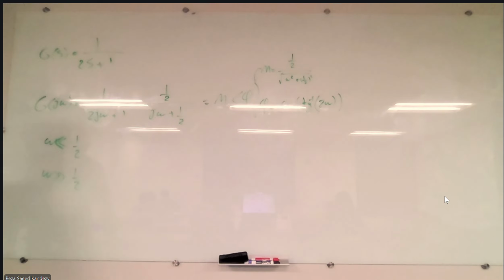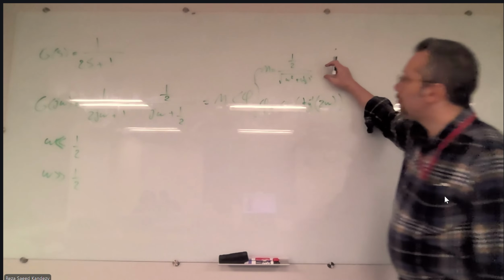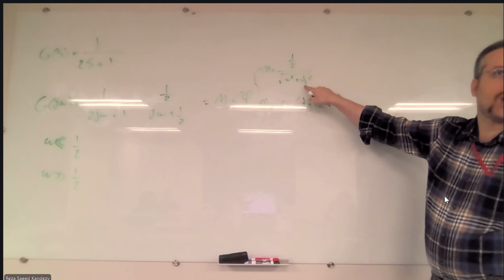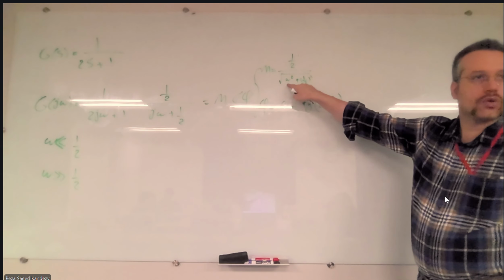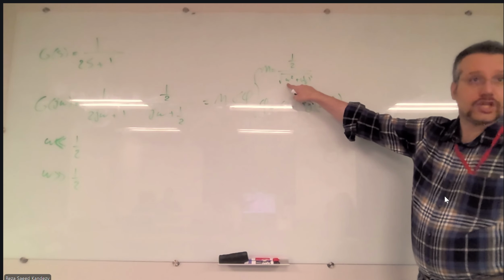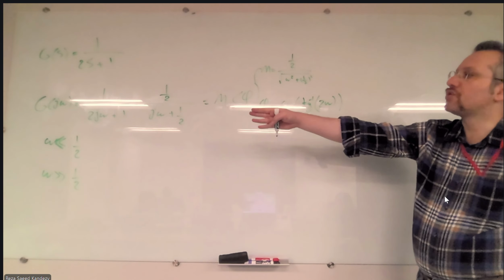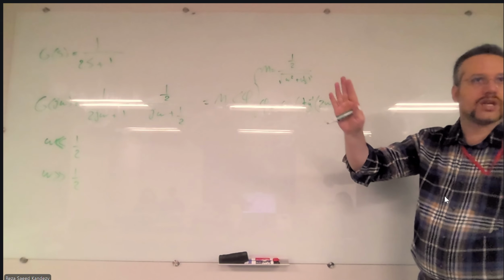Now let's go back to the situation that we have. If omega is way less than 1 over 2, for the magnitude, what's going to happen is that this 1 over 2 squared would dominate under the square root. So we can ignore the omega. Remember, asymptote lines are basically approximations. If it's like 0.001, we still have a number here, but we are using approximation, so we can neglect that.